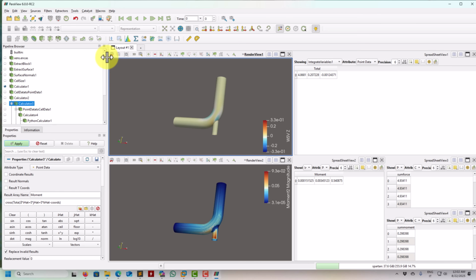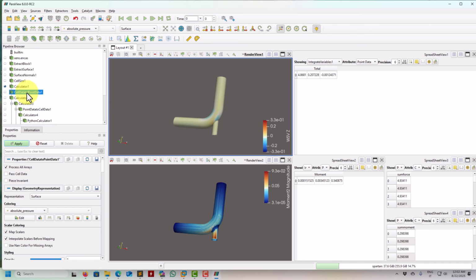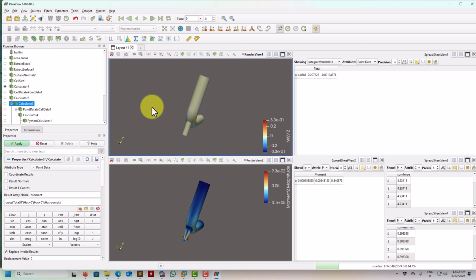Be careful also as you export in cell-centered or point-centered, also the vectors. You see here that, for instance, we needed to assemble the wall shear vector just to make your life easier, but it's not like it would change much. So yeah, this is it. Now we have covered this case, different datasets, different solvers, different methods to do things. And one cool thing I mentioned is that to compute the center of pressure, you can come here and find a point where the moment is zero. So that's all.